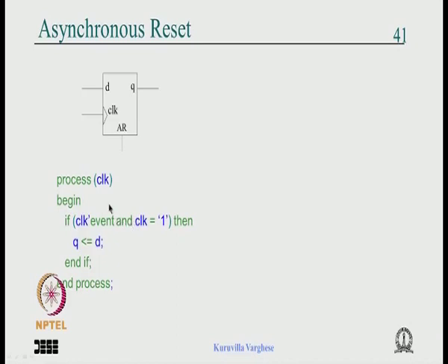Naturally that means it is no longer the same process, since we are looking for both the simulator and the synthesis tool together. Basically the reset is asynchronous, so the reset has to be in the sensitivity list, because any time reset happens then Q has to go to 0. So we need to write the reset.